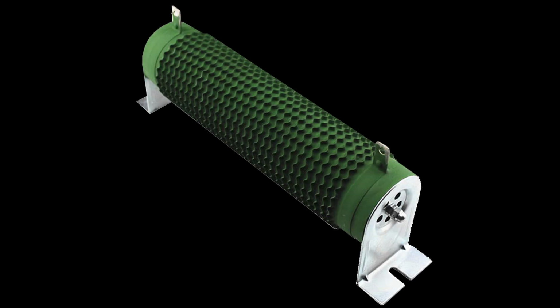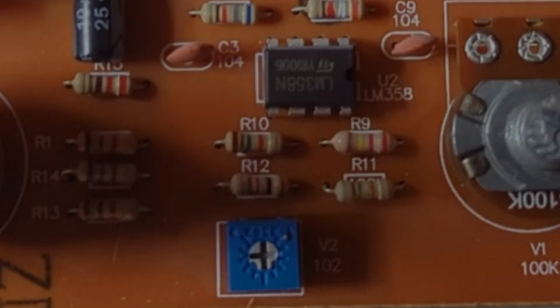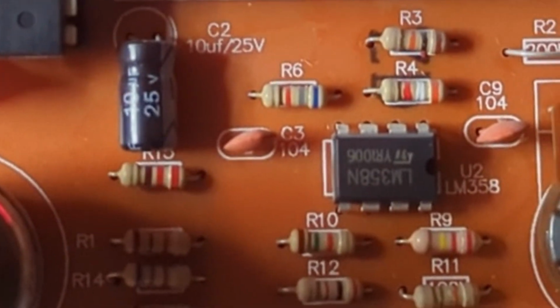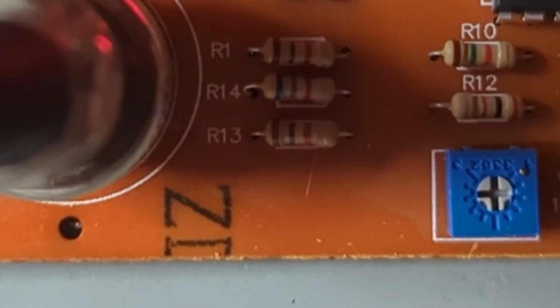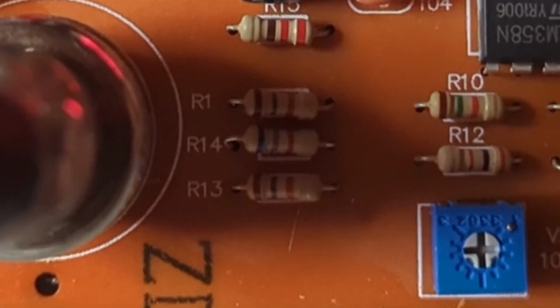Usually the power rating is directly proportional to the size of the resistor, with tiny surface mount resistors having ratings as low as 30 milliwatts or 1/32 of a watt, and large industrial resistors having ratings of hundreds or even thousands of watts. As long as you keep the average power dissipated in your resistor below its rating, the magic smoke will remain trapped forever and it will continue to work normally.